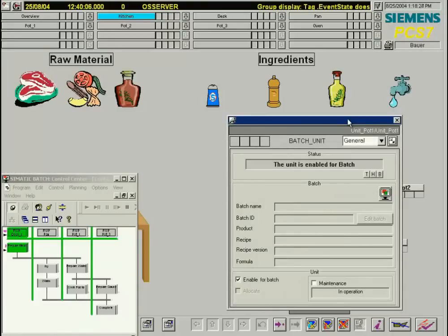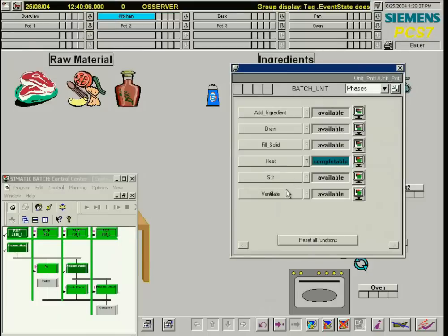You have seen how a recipe phase created in this way can be included simply and intuitively in a master recipe. The parameters specified in the SIMATIC Manager, such as set points, appear in SIMATIC Batch as recipe parameters, and the required values can be entered there. The procedure as shown here is only possible because of the tight integration of SIMATIC Batch with the modern SIMATIC PCS 7 process control system.